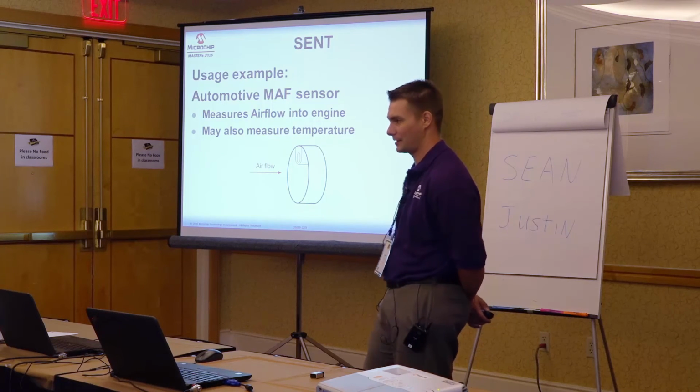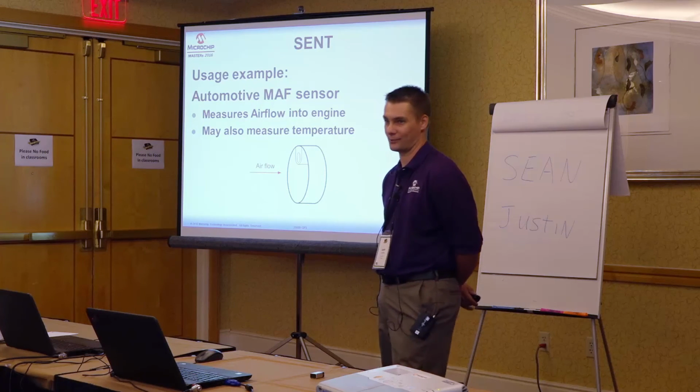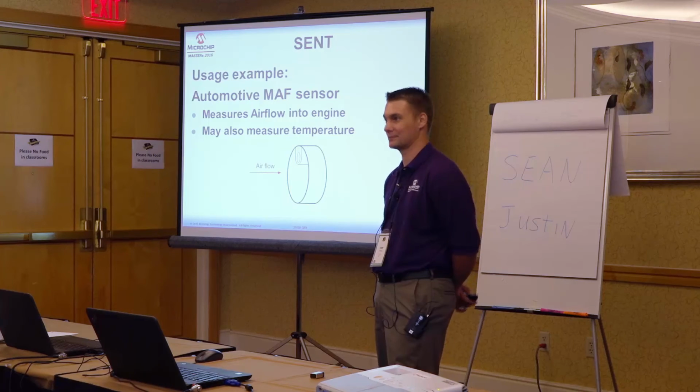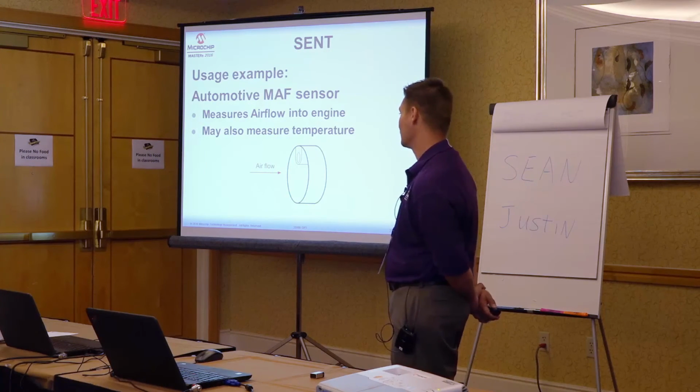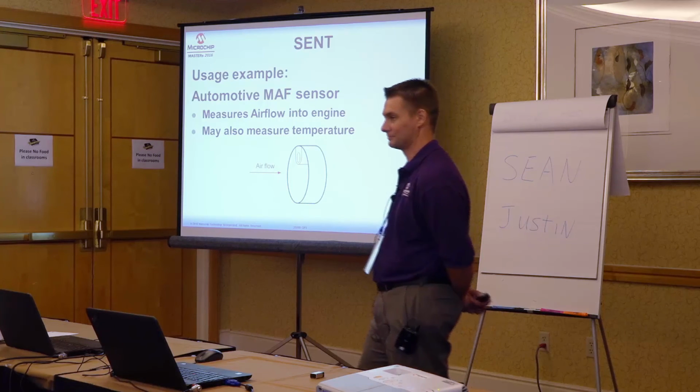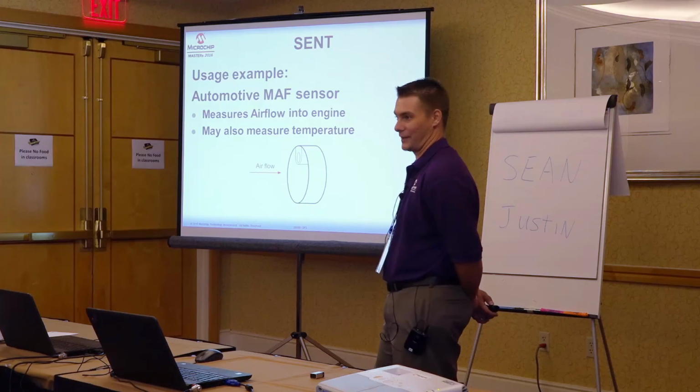So a lot of them are based on a hot wire with the air going across the wire, and it cools it off, changes the resistance. Therefore, you can measure the voltage, and there's your airflow rating. And usually that number is sent to the computer in a raw, just counts or a value.